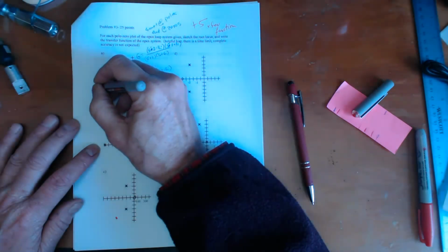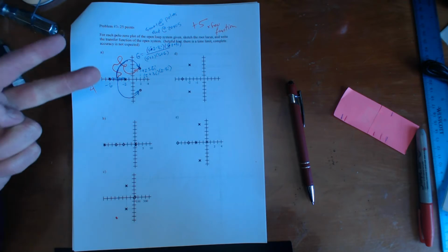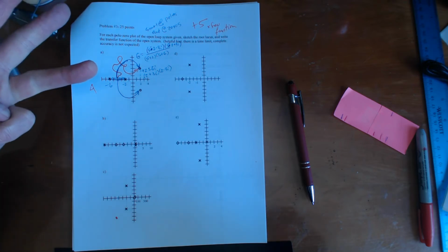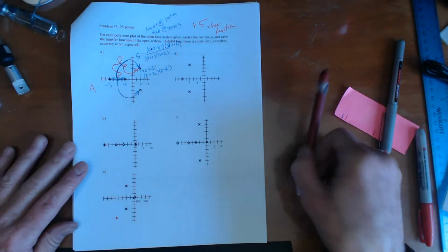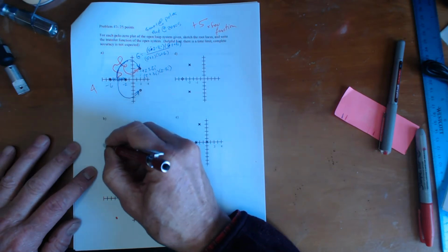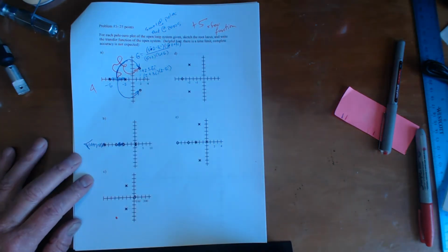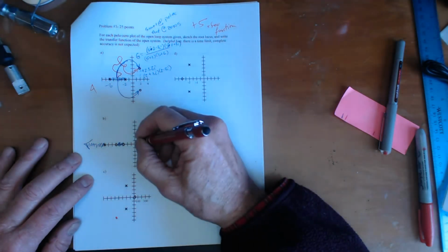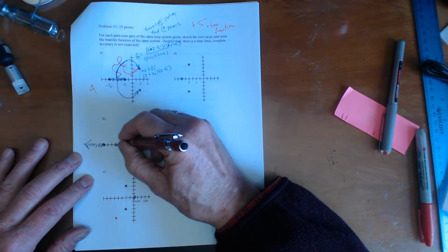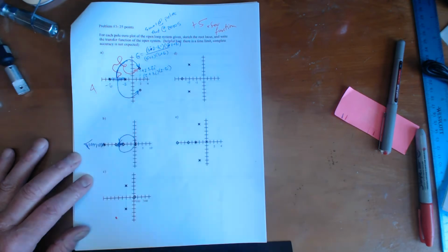Overall, and then 4 points for each one of these things depending on how you did it, because you've got the real axis segments, you've got the infinite asymptotes, you've got the start and end points, and then maybe a point other than that. Okay, so here's 1, 2, 3, 4, 5, 6. So here's the real axis segments for that thing. They start at the open loop poles and end at the open loop zeros. So I'm just going to say somehow this has to break in here and go this way and that way.